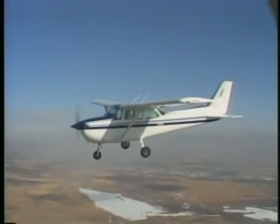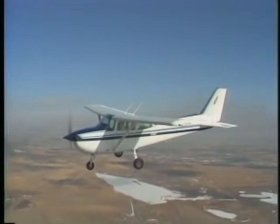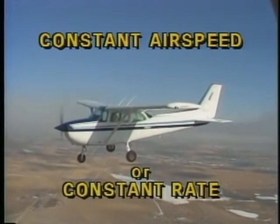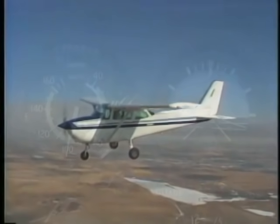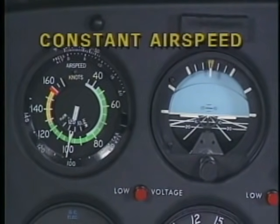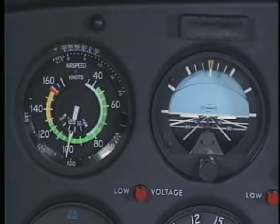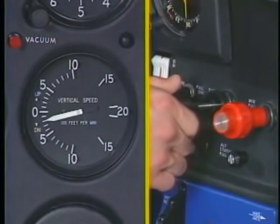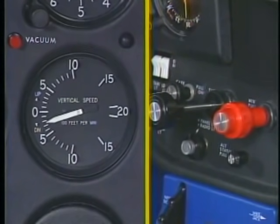When changing altitudes in instrument flight, you should perform either a constant airspeed or constant rate climb or descent. To maintain a constant airspeed, initially adjust the pitch attitude of the airplane by referring to the attitude indicator. During this maneuver, you normally hold a constant power setting. However, if you desire to change the rate of descent or climb, you can vary the power.